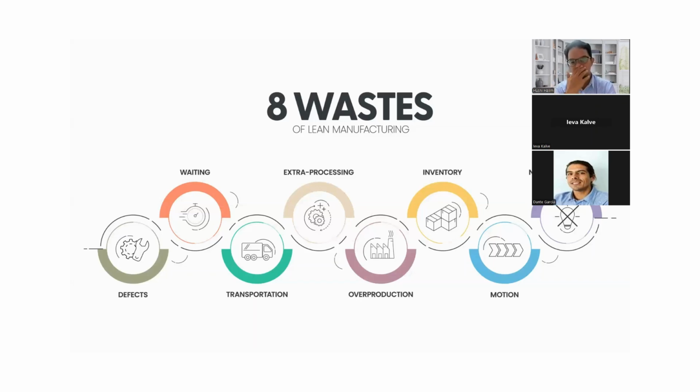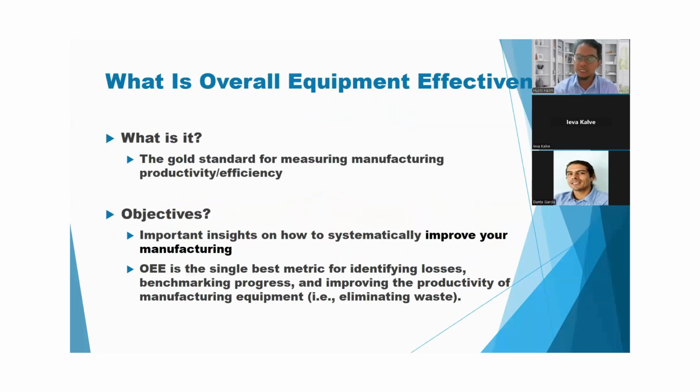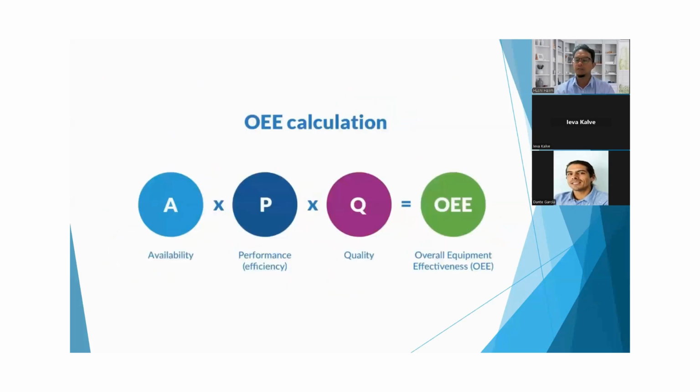So here I'm trying to just give a way of a calculation on the OEE. OEE comes in three parts of the calculation. It comes with the availability, multiplied by the performance, and multiplied by the quality. These are three factors that contribute to the OEE calculations. Availability is how much time the machine is available and running. Let's say if you're running 10 hours and then the machine itself is running for 8 hours of the 10 hours, that's probably 80%. That's 80% of the time.